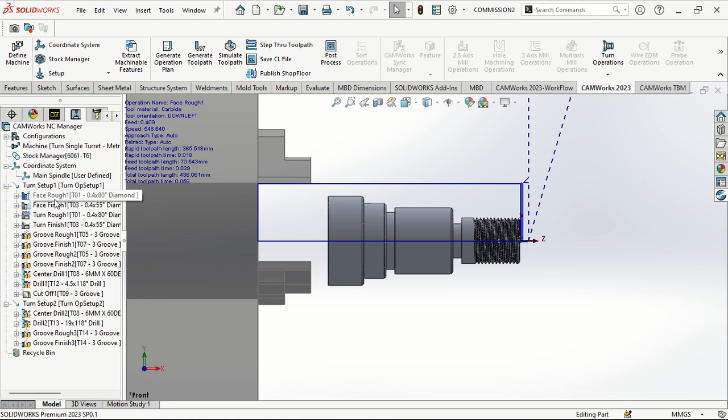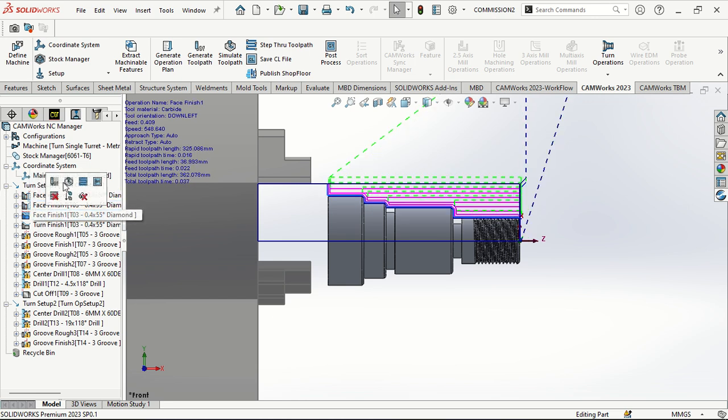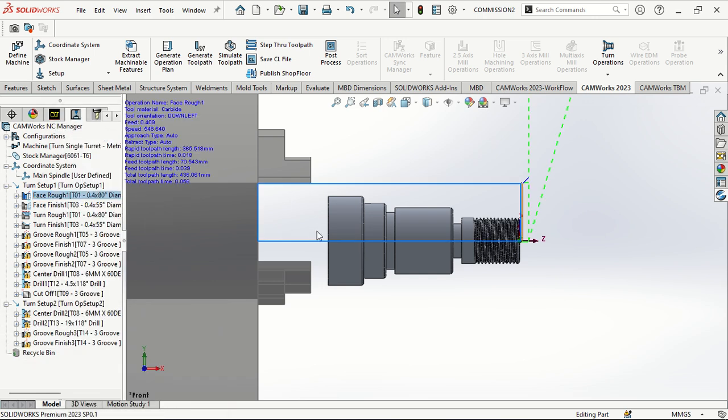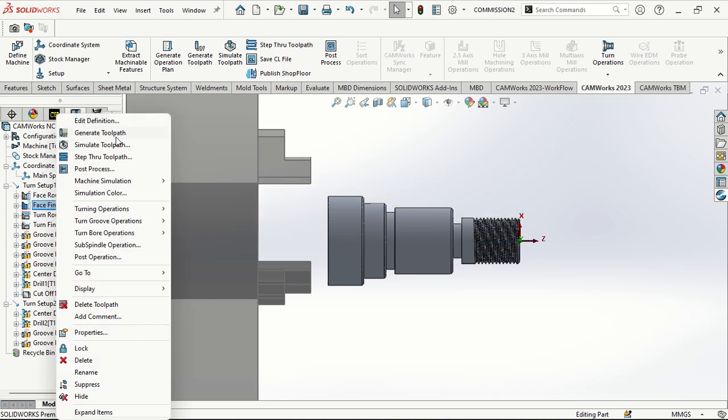And then here you see it has put this. If I click next, I can also go and update one by one. Once I finish, say maybe here I've done something, I click generate tool path so that it updates because I've made a change. Once you make any change, you click on generate tool path.